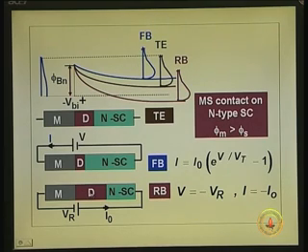Now, when you reverse bias, the entire potential is plus here, the same polarity as the built-in potential. So, if that were the built-in potential between this point and that point, it has gone up now by an amount V r. This is the extra voltage that you applied additional to the built-in potential. So, the electron distribution tip is now at a much lower energy than that. So, these electrons are not able to climb up the barrier. So, the current is only due to these electrons which are there from left to right, or from the metal